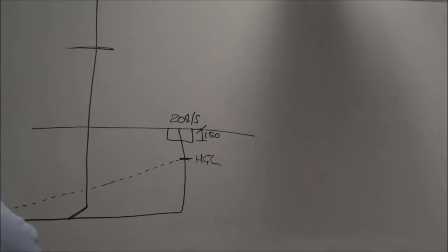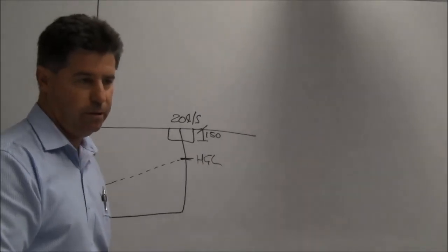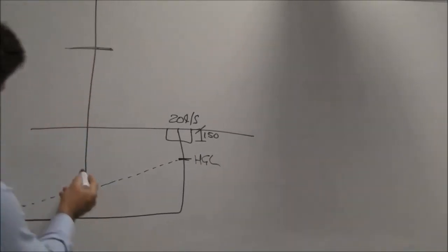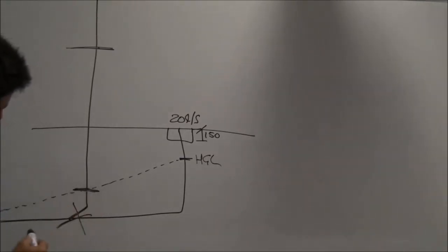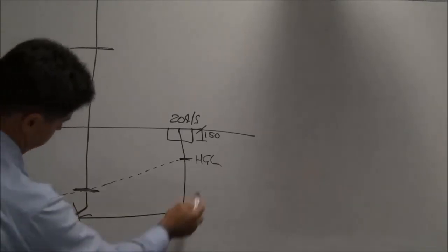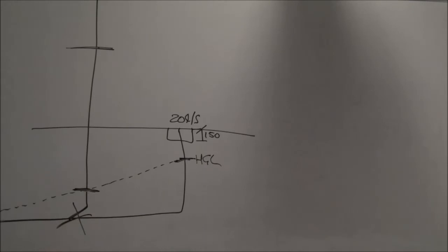You're actually working from the outlet coming back, because you're working out your losses right through the system, right to the end, right to the beginning. Because the loss from here to here may only be small, but from here right through to here is obviously a lot greater for the gradient. So you work from the outlet back. Always work from the outlet back to where there's a hydraulic grade line.